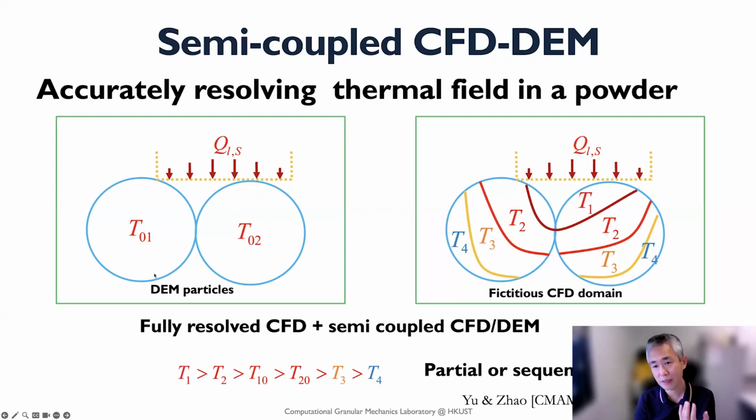So you are going to have a gradient of the temperature field within each individual particle. This creates a progressive melting process, and sometimes a particle is only partially melted and leaves the other part as a solid part here. If we treat that purely in DEM, of course, there's still a technical way to do that, and for each DEM particle I would do high resolution temperature field simulations.